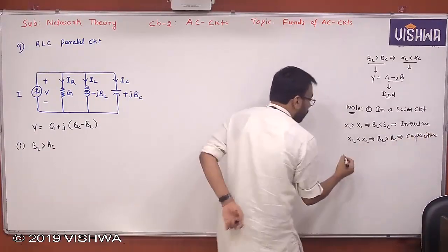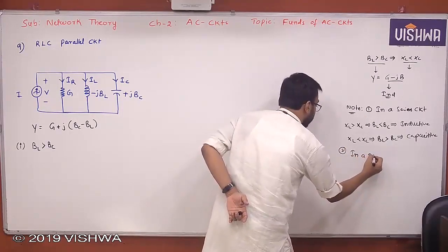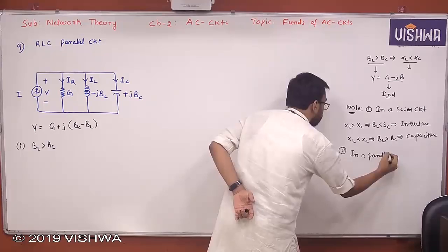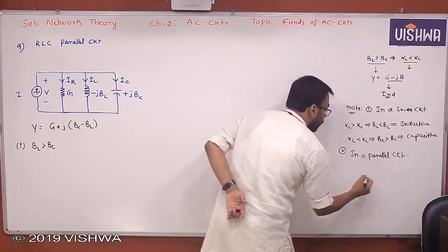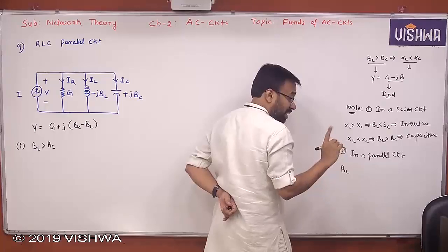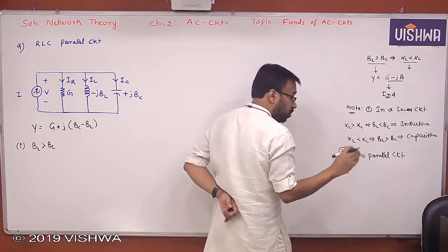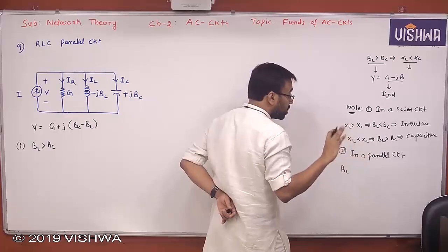Understand? In a parallel circuit, now you must take susceptances, not reactances. Whenever you take a parallel circuit, you must always compare susceptances, not reactances.